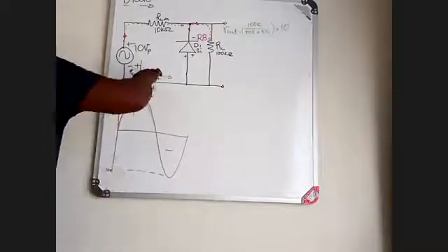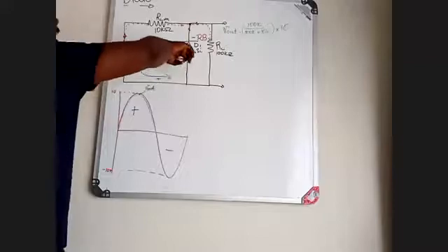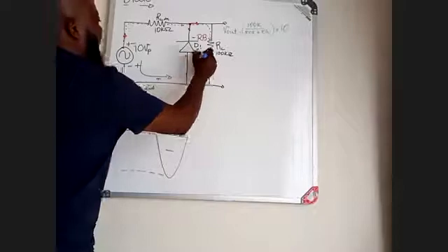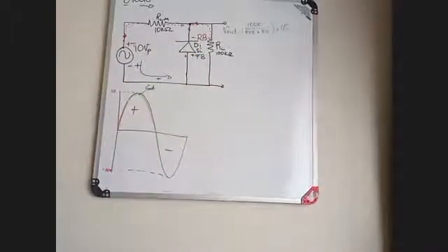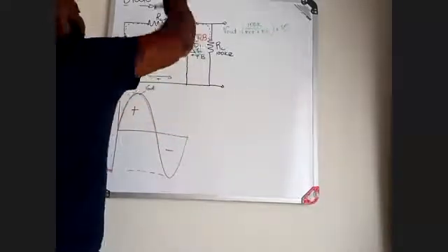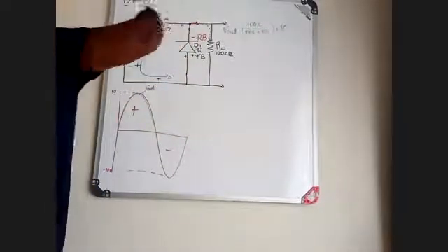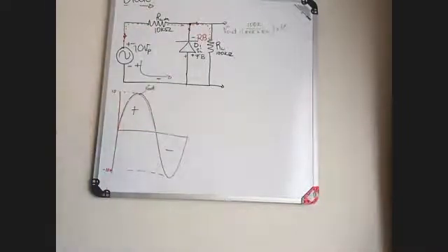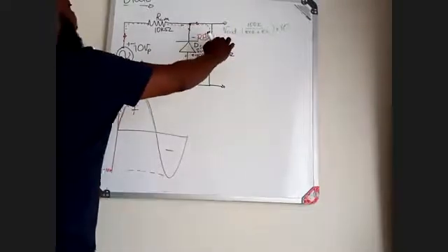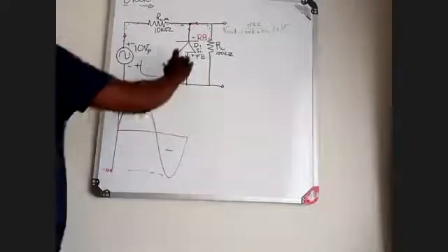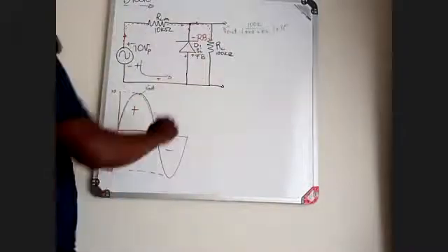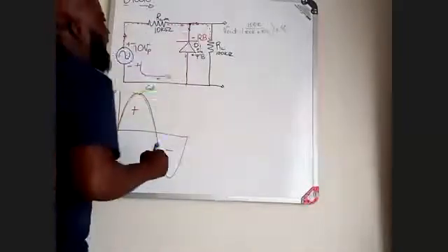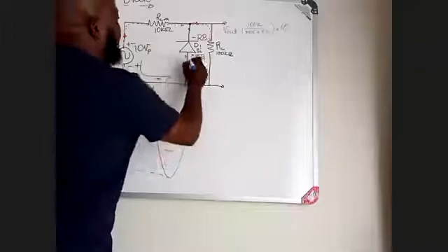there. Then the positive, with respect to how your current is flowing and your diode, is going to force your diode to go into forward bias mode. Now, when the diode goes into forward bias mode, which means now the internal voltage has been established, or your barrier potential has been established, the switch has been closed, which means now you are allowing the current to flow. Because this component and that component are parallel to each other, whatever I'm going to measure here, during the process whereby this component is forward biased, because it's silicon, it's going to be what? It's going to be your